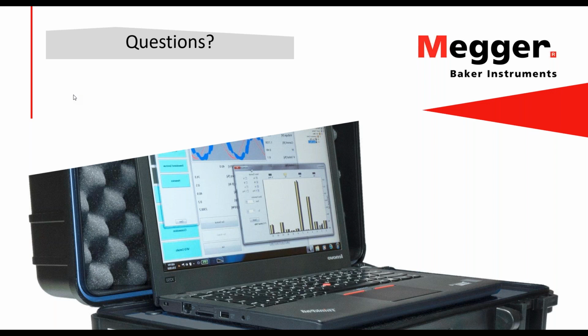So what I'm trying to get at is that you don't need to know the number of rotor bars, because the analysis that's done will give you frequency components and they don't need to know the number of rotor bars. Of course, if you know the number of rotor bars, you can use that information to realize that there may be a problem here that otherwise you would not be able to interpret properly. I would say, all right, but it's not necessary to know the number of rotor bars.